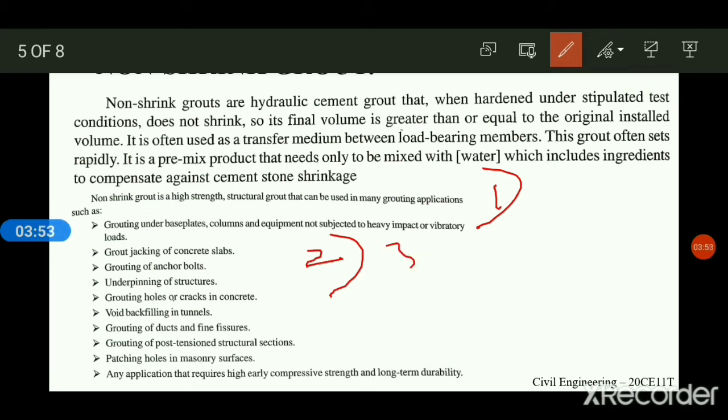Next, for water reducing components, naphthalene water reducer, melamine water reducer, polycarboxylic water reducer, and other superplasticizers are used. For thickening and water retention components, low viscosity cellulose ether, redispersible latex powder, etc. are used.